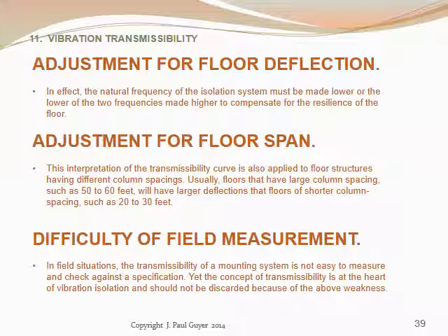Only when equipment bases are supported on large, extensive portions of rock bed can the transmissibility curve be applied directly. The interpretation of the transmissibility curve is also applied to floor structures having different column spacings.